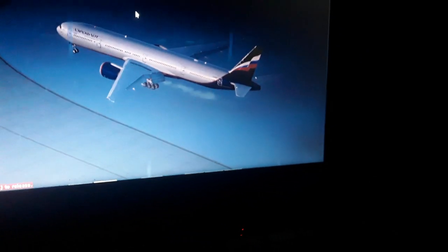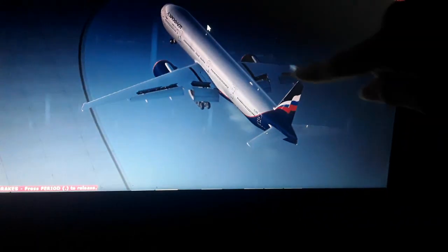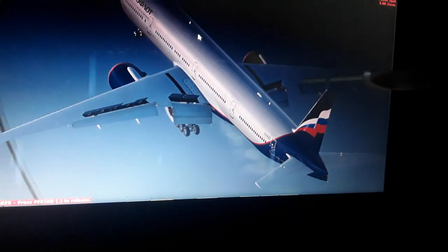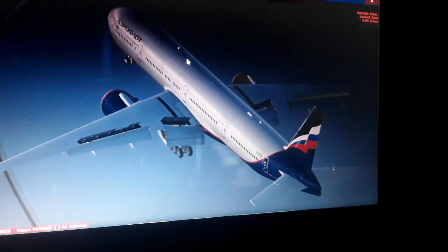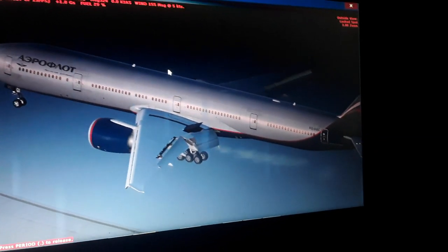Now I'm going to show you also the flight controls. You can see the wings of the aircraft here. You can see the mean aerodynamic chord position. You can see the aircraft surface area of the wings is holding the aircraft weight in flight. Also, the mean aerodynamic chord position is the position where the maximum aerodynamic lift occurs, or also is where the stall of the aircraft wings begins above the surface, in the top surface of the wings. The flow of the air becomes detached.